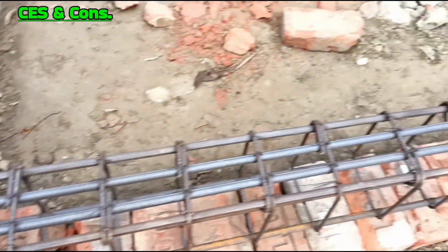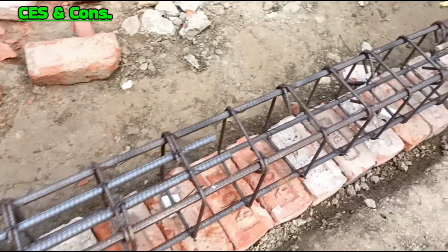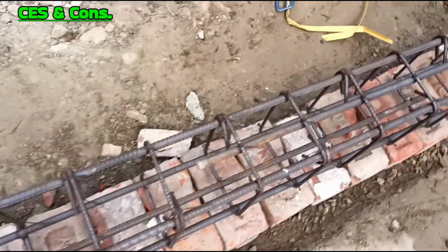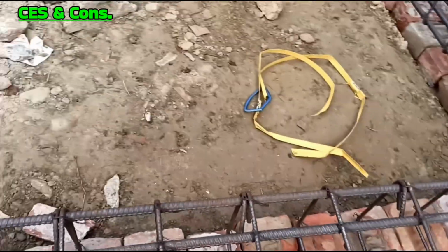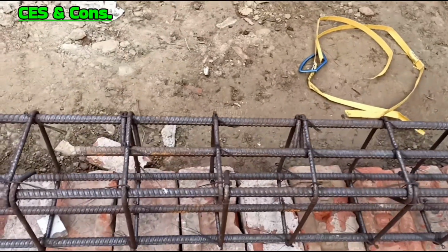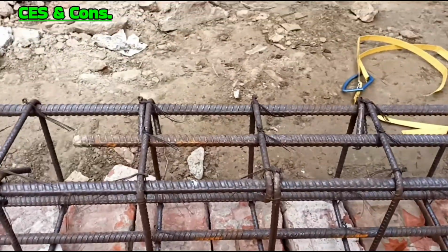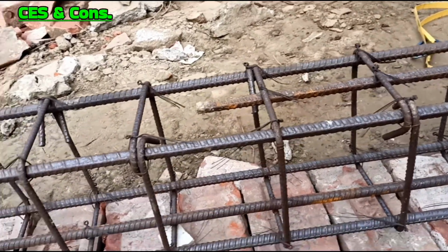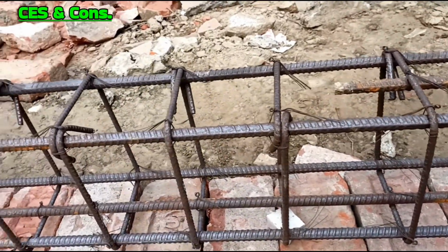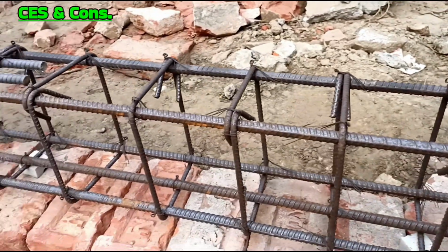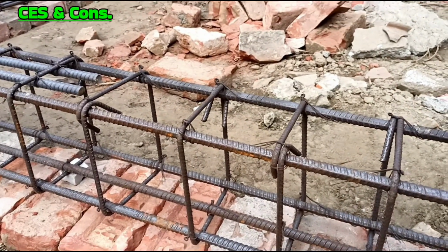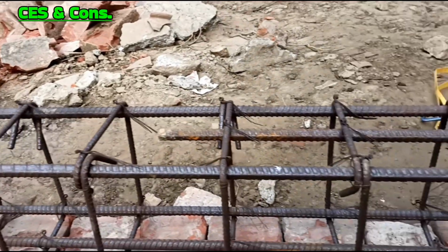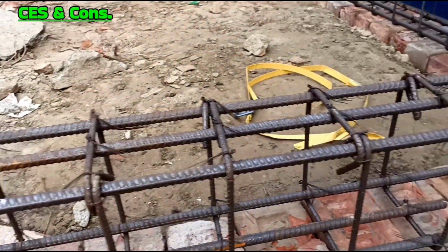In seismic regions, plinth beams play a role in resisting lateral forces, which can cause alternate tension and compression zones on both faces of the beam. In the case of an RCC plinth beam in a building, there are generally no upward earth pressures acting directly on the beam unless the soil below the beam is expansive or exerts heaving forces due to specific conditions like swelling clay or freezing water content in the soil.